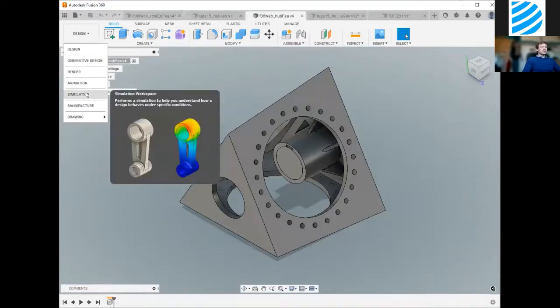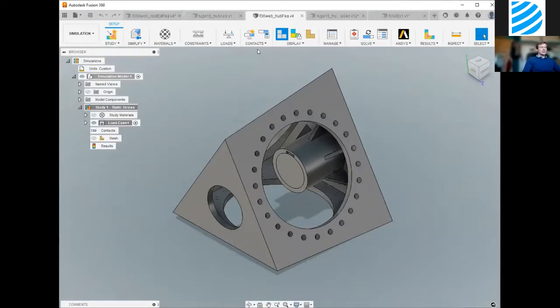So I've already set up the simulation since we've already gone through it once with the root extension. The point of this one, not only was to show the idea of drawing a new model for the FEA study, I'm going to show how I go about using symmetry to simplify the analysis, and it also speeds it up. You need less computing power.